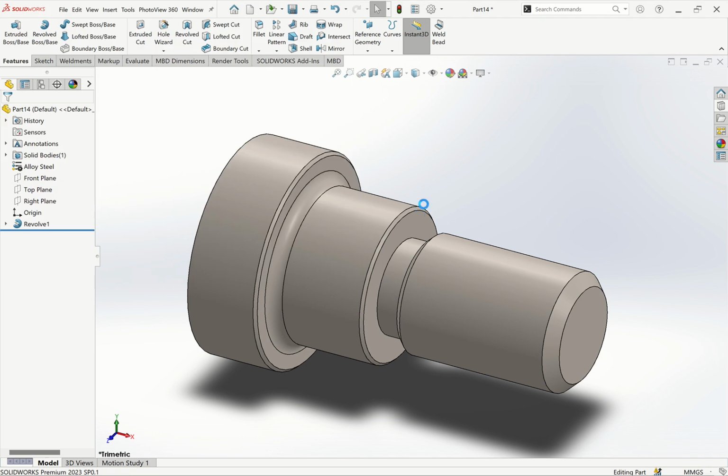Okay, we save the part. We have this. So first way of putting thread on in SolidWorks, once you have your design, ensure for external thread, because I want to use M20 by 2, which means it's metric thread, the major diameter is 20 and I have a pitch of 2, so I'm having a diameter of 20 here.